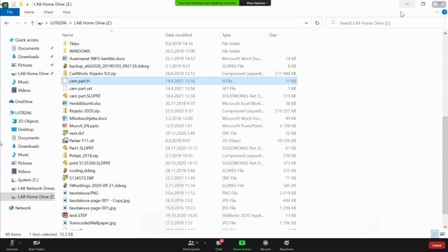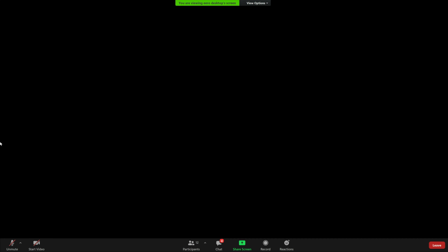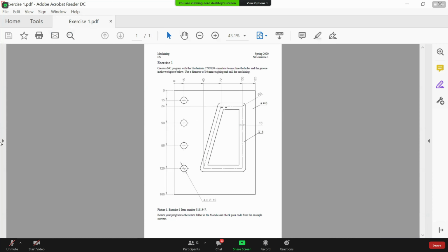Once again, if we imagine how we did this one last year, machining this pocket. It was done so that we selected a 10mm roughing end mill that is able to machine a pocket with the width of 10mm easily with a single pass, so that if we program our tool from this point to that point, from this to there, and from here to there, and there, we end up with the desired pocket.